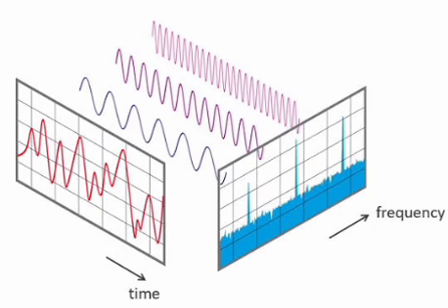The discrete Fourier transform is basically the Fourier transform of a sampled signal repeated periodically. The number of points in the DFT is known as the N-point DFT. The definition: consider a sampled and periodic signal x[n].